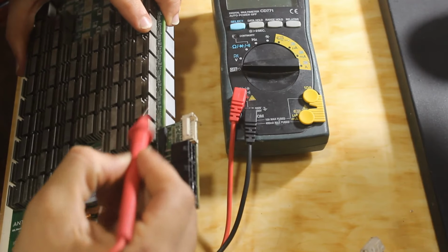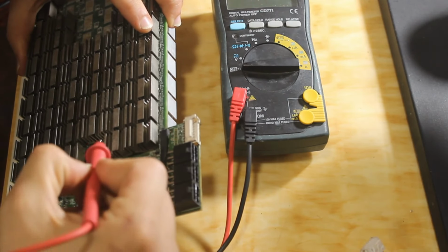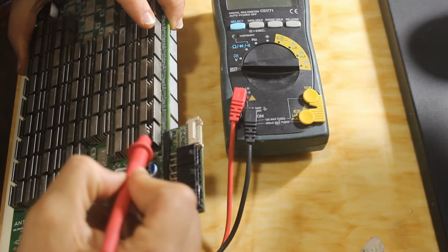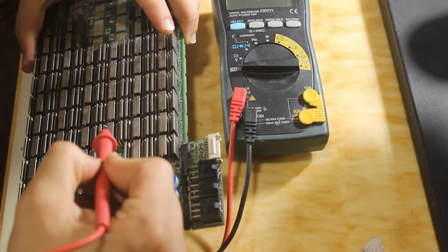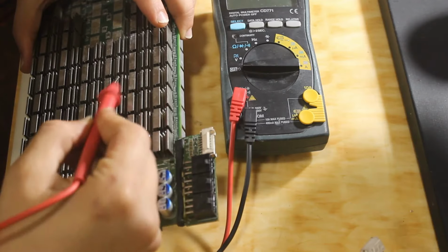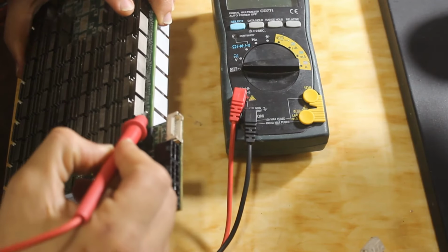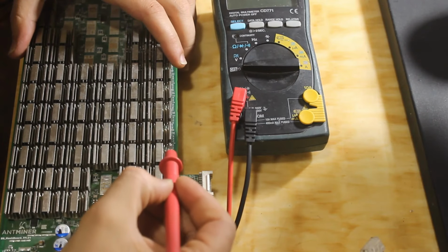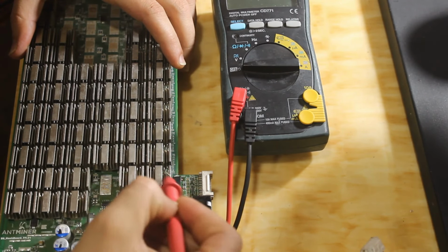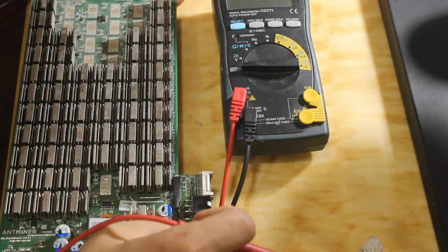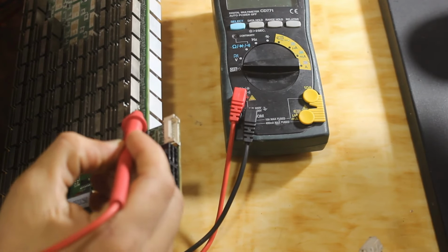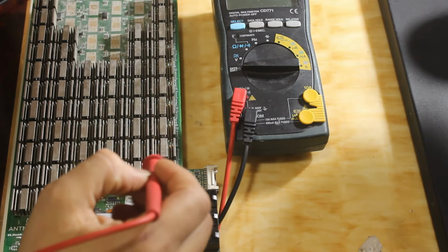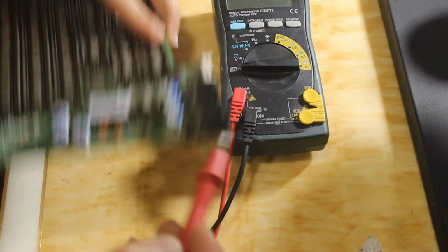For signal, we have 4 signals. They go from 0 in this direction, then from here to here, from here to here, from here to here. And the signal RI goes vice versa, from here to here, just RI. Let's talk about the first signal, CLK. It should indicate 0.9. This board is faulty, it's giving me 0.6.